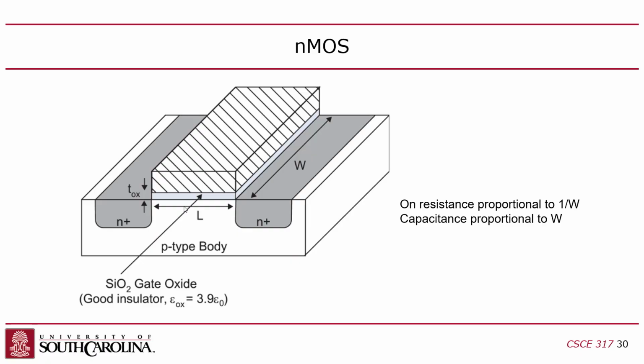They have to move. They physically move. Those electrons and holes physically have to move. And they don't move at the speed of light. They move actually a lot slower than that. That's referred to as the carrier mobility. Okay? So by making the channel length, in other words, the distance between the source and drain, or the distance between the diffusion areas, as small as possible, the transistor will switch faster because the carriers can get across that channel faster if they have less distance to cover, right?